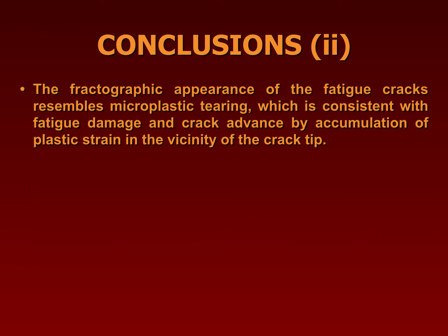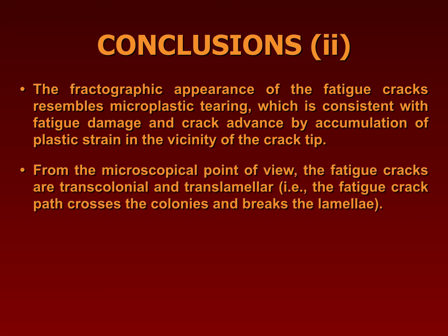The fractographic appearance of the fatigue cracks resembles microplastic tearing, which is consistent with fatigue damage and crack advance by accumulation of plastic strain in the vicinity of the crack tip. From the microscopical point of view, the fatigue cracks are transcolonial and translamellar. It is, the fatigue crack path crosses the colonies and breaks the lamella.